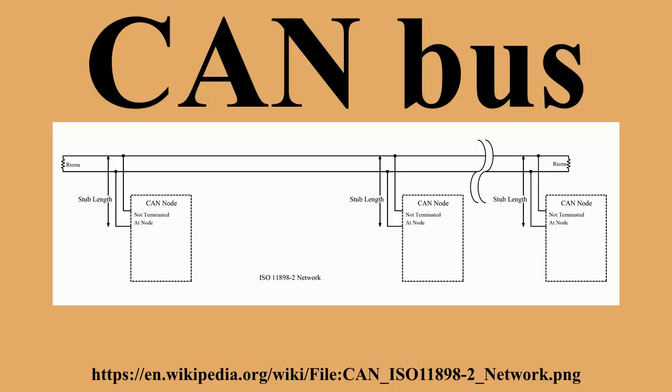RS-422/3, RS-485, etc., which employ differential line drivers, receivers and use a signaling system based on the differential mode voltage of the balanced line crossing a notional 0 V. Multiple access on such systems normally relies on the media supporting 3 states and is dealt with in the time domain. Multiple access on CAN bus is achieved by the electrical logic of the system supporting just 2 states that are conceptually analogous to a wired OR network.